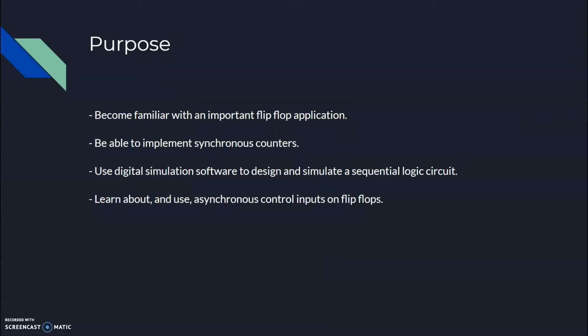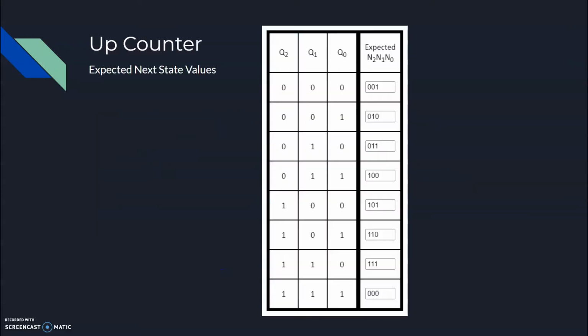The purpose of this lab was to become familiar with an important flip-flop application, be able to implement synchronous counters, use digital simulation software to design and simulate a sequential logic circuit, and to learn about and use asynchronous control inputs on flip-flops. So the first circuit we were to design was an up counter.